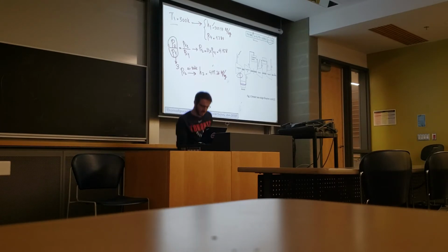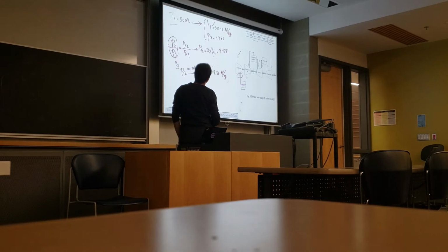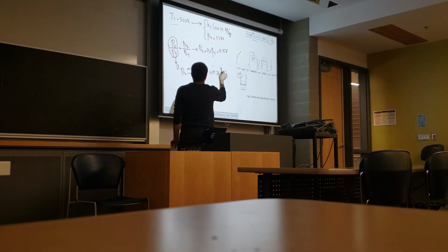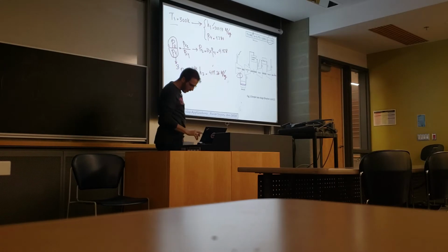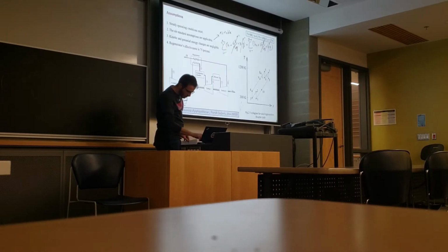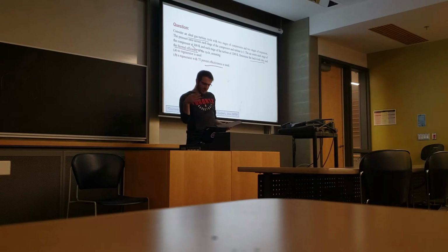So there is one thing here, because we have this equal compression ratio. Basically, we begin with 1 and going to 2, and then 3 has the equal temperature as 1. You see, in the question, we have each stage of compressor at 300 Kelvin. And because the compression ratio is the same, and it's air, at the end of each compression the temperatures are also the same.